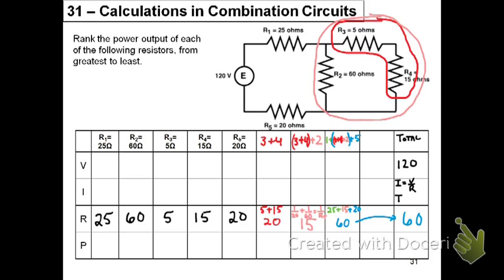Using Ohm's law, if we know the voltage and we know the resistance, we can determine that the current is 2 amps. Also, from our series circuit ideas, we can now say that that 2 amps is going through resistor 5 and resistor 1 as well. Likewise, the combination of resistors 3, 4, and 2 also experiences 2 amps. However, each individual resistor does not experience 2 amps. Labeling, we can now see what we have in our total circuit.